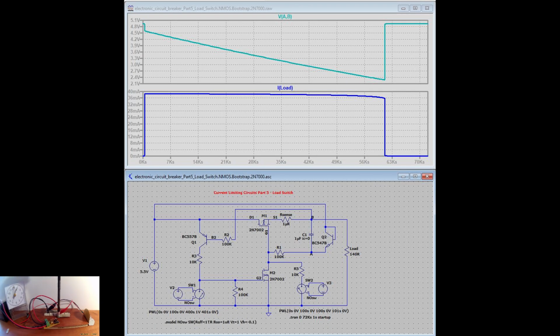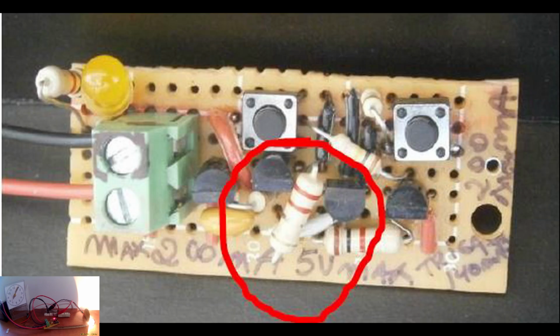Before the previous circuit was built, a smaller one, using MOSFET 2N7000 for M1 and M2, was built. It stayed on for 6 hours without the R-sense resistor, driving a 40 mA current. This is the circuit running in the smaller window during this presentation.